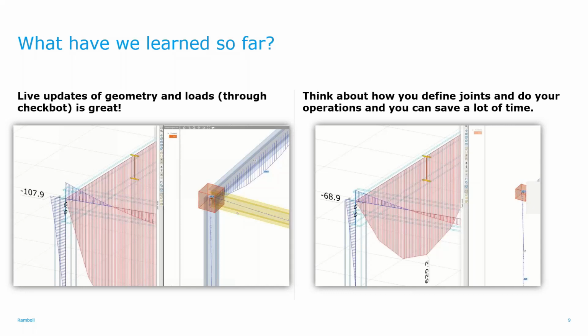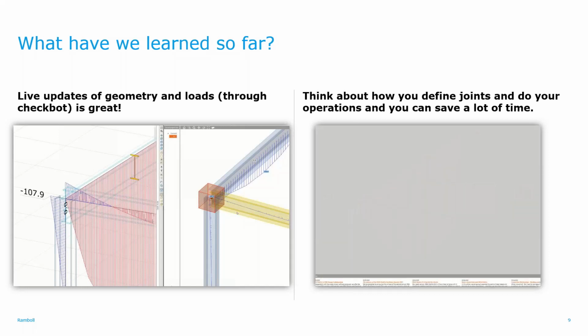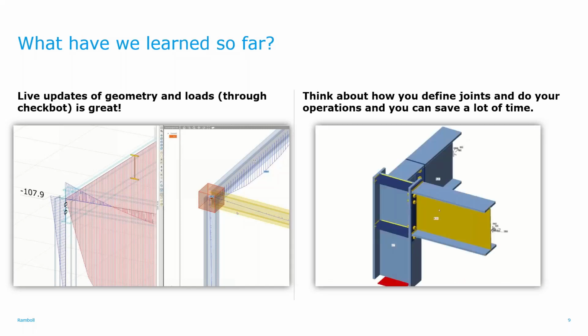You saw in the picture before that I had some stiffeners and an end plate that were all defined together with the member, and I also had my bolt positions defined. In this example, which should show in a second, you'll see how the stiffeners, the end plate and the bolts are all following along. The design might not work, but at least we don't have to deal with any errors in the connection design because we've changed the member types. So let's wait a second for that to come up.